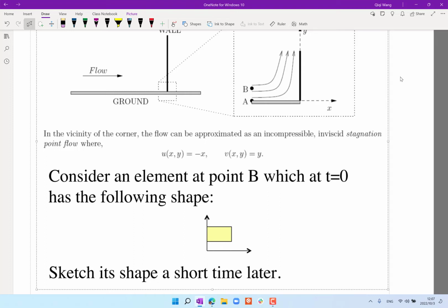And also, what is the vorticity here? Zero, right? Because du dy is equal to 0, dv dx is also equal to 0. So du dy is equal to dv dx. Okay, so we can use Bernoulli. That just means we can use Bernoulli across streamlines. And the flow can be approximated at least as a composition of the basic elements.